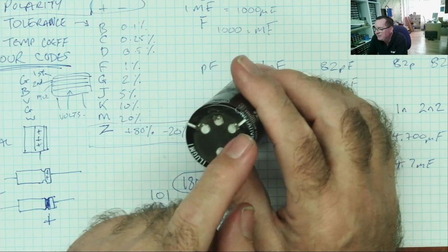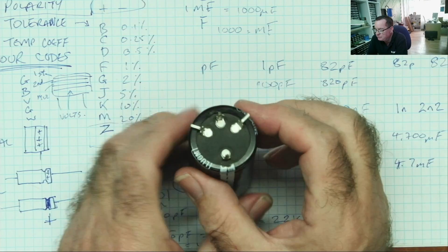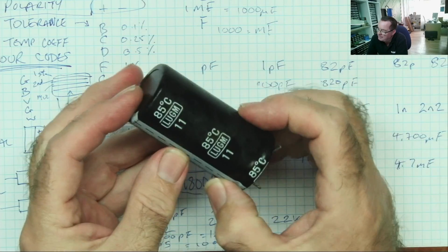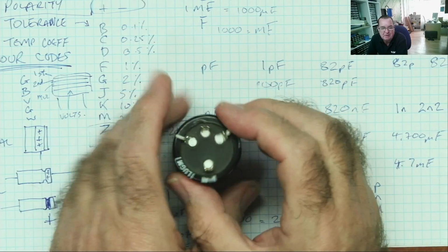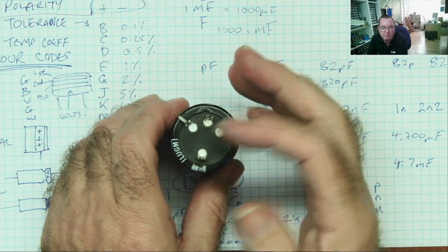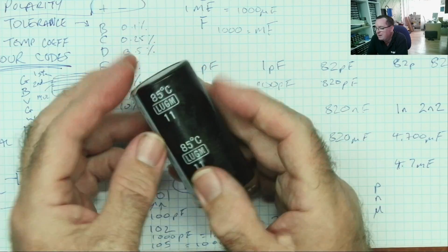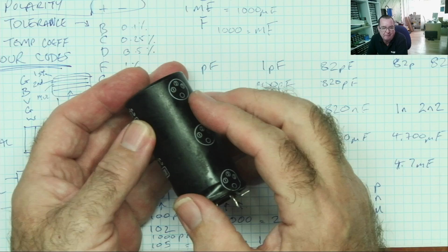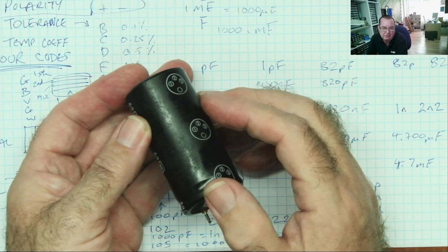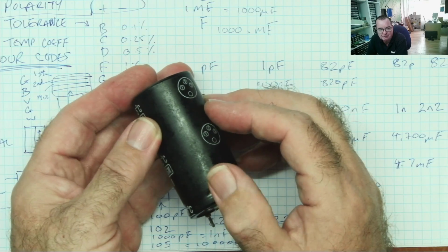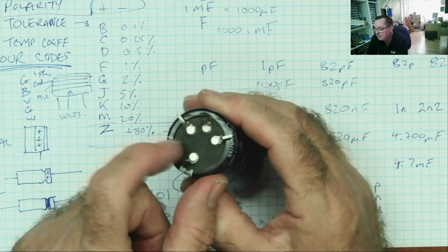Also with capacitors like this, especially on vintage equipment, again in this valve era, vacuum tube era, you'll find capacitors like this or similar to this that actually have more than one capacitor in them. They'll have one common terminal and then maybe 3 other terminals. If you look on the side, it'll tell you it's 25 microfarads at 20 volts on one coloured dot, and another coloured dot is something like 5 microfarads, 400 volts or whatever. And these terminals actually have coloured markings on here.